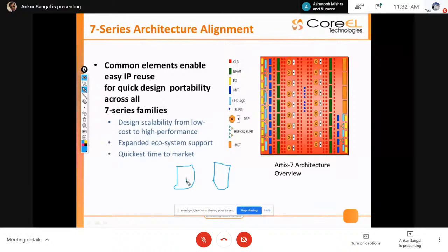This is some A logic, this is some B logic internally. It is connected here to here. This is input to register. This is register to register. This is register to output. And this is input to output. Okay, so in any circuitry there are a maximum of 4 types of paths. No 5th path is available. One is your input to reg. This is your reg to reg and reg to output. And after that, input to output, or output to input. This is like a feedback path. Okay, so a maximum of 4 types of paths are available in any digital circuit.